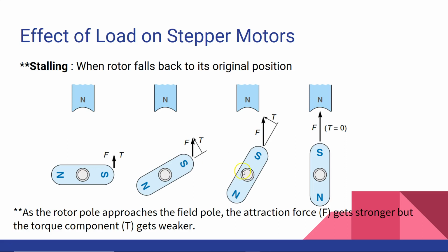Here in this picture you see our rotor and this is our stator pole, and we are assuming that this stator pole is energized. If it is energized, then this rotor will try to align with this energized stator pole, and it will move towards the left. The south pole will try to align with this stator pole.